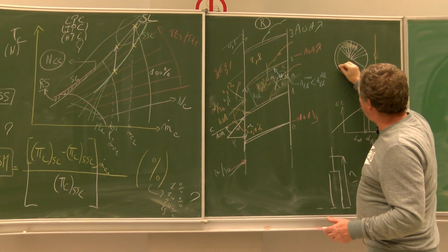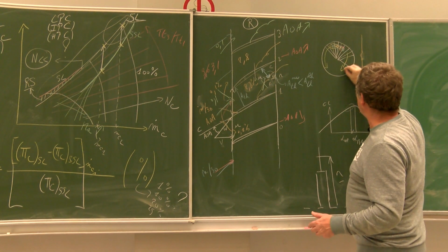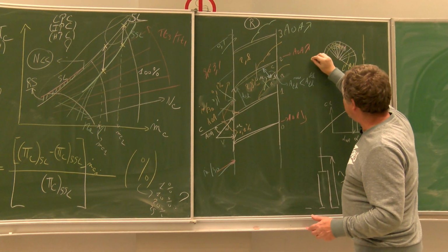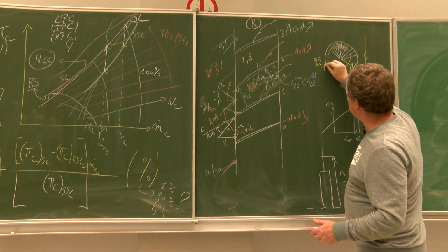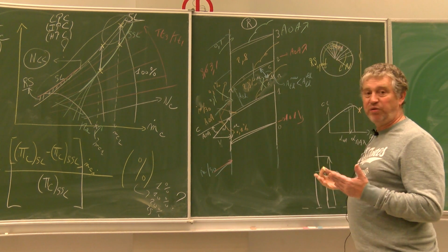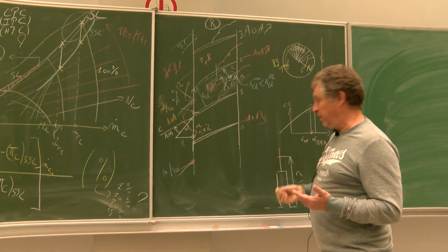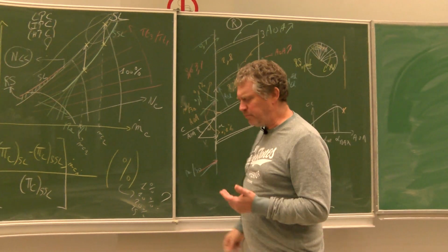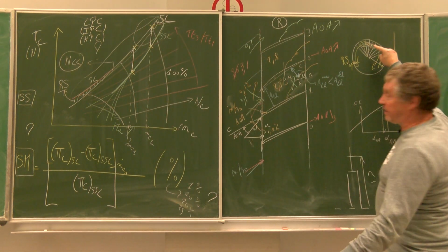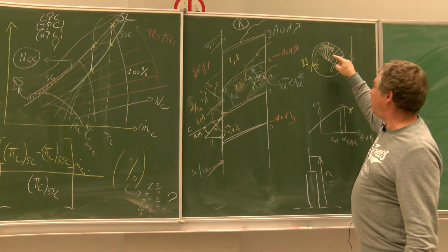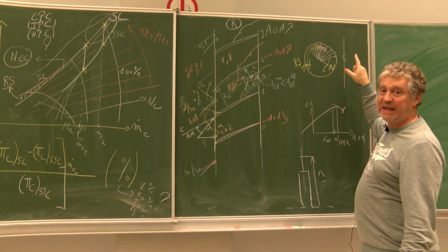And you see that this pocket is rotating compared to the rotation direction. You will have the rotating stall speed going in the opposite direction compared to the rotating stall of the compressor. And so the problem is coming back where it has been created. So vroom, vroom, vroom, it's rotating like this.